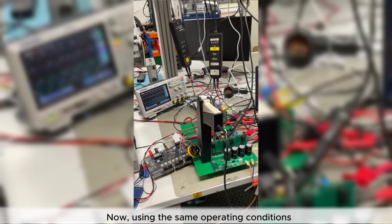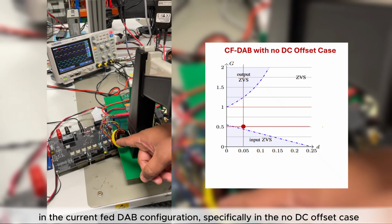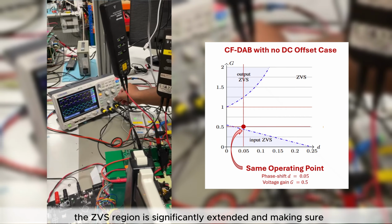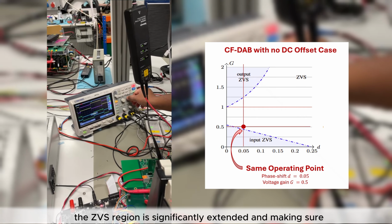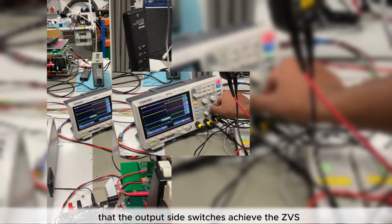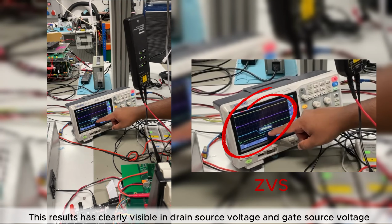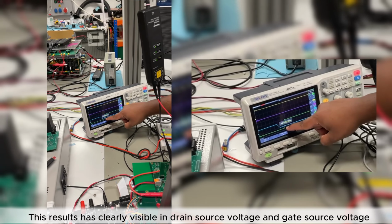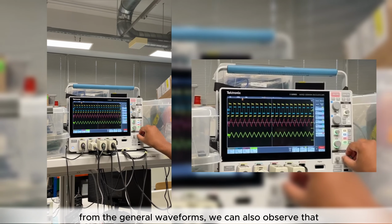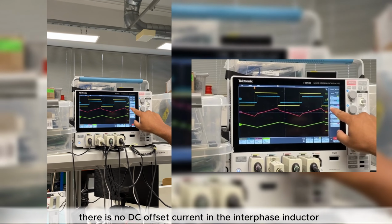Now, using the same operating conditions in the current-fed DAB configuration, specifically in the no DC offset case, the ZVS region is significantly extended, making sure that the output side switches achieve ZVS. This result is clearly visible in the drain source voltage and gate source voltage. From the general waveforms, we can also observe that there is no DC offset current in the interface inductor.